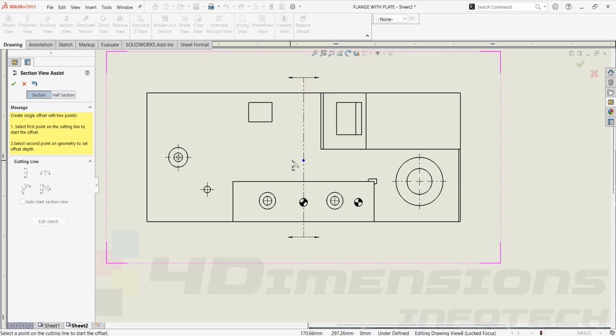So before coming to its center alignment or before starting the hole itself, the alignment of this dot I'll keep in such a way that this hole will not intersect the alignment. I'll put it earlier only, say at this point, and then we will drag this offset line to take single offset and place it on this center of the counter bore. You can see the alignment I have taken a little bit earlier so that it should not get aligned with the circle's alignment. Say it OK.